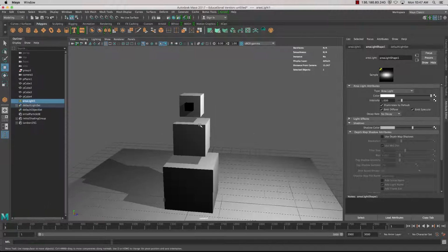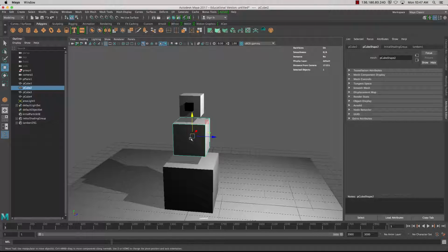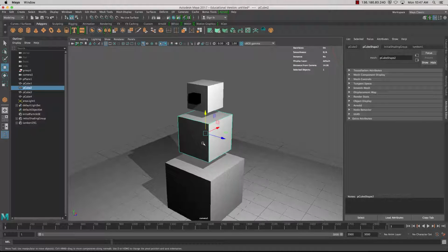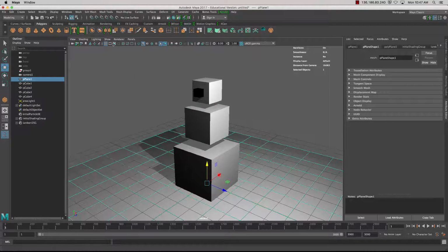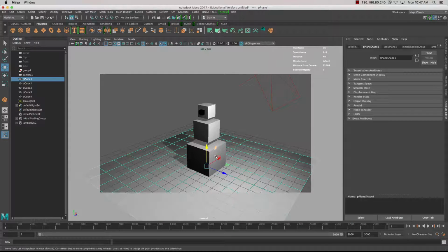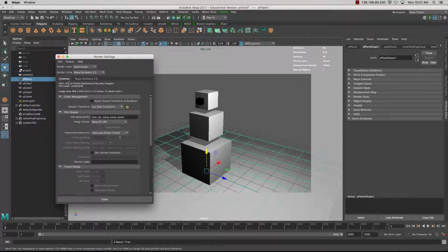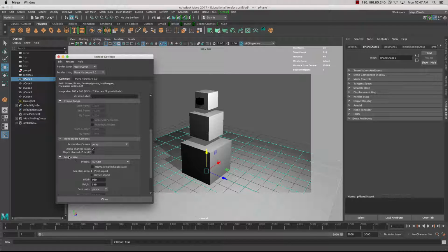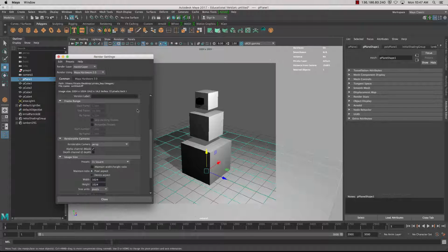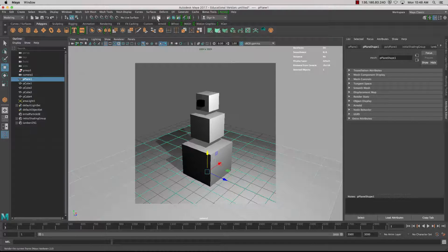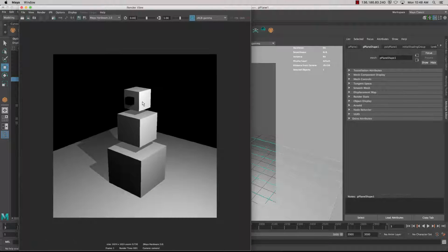And if I want to line that up, if I select an object and focus in on it and rotate it out and spin it back out, then I can sort of line it up nicely like so. I can even see the framing of the settings there like so. So the framing of the resolution is set inside common attributes under image size. So if I wanted to make it for 1K, I can do that inside there as well. So it's nice and square. So just bring up that window, render it out.